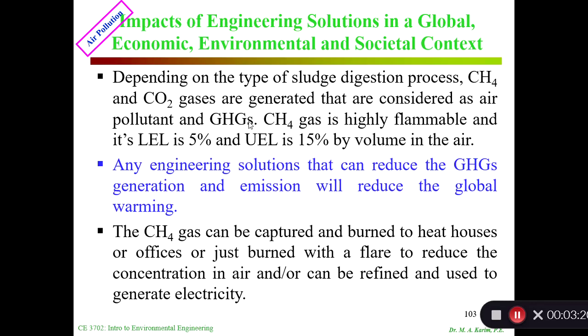Methane gas is highly flammable, and its LEL is 5% and UEL is 15% by volume in the air. Lower explosive limit and upper explosive limit. An engineering solution that can reduce the greenhouse gas generation and emission will reduce global warming. So the methane gas can be captured and burned to heat houses or offices, or just burned with a flare to reduce the concentration in the air, or can be refined and used to generate electricity.